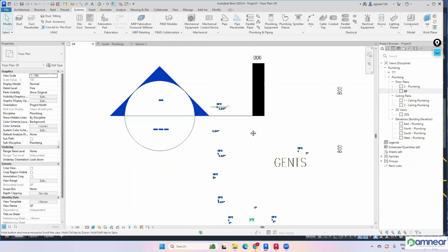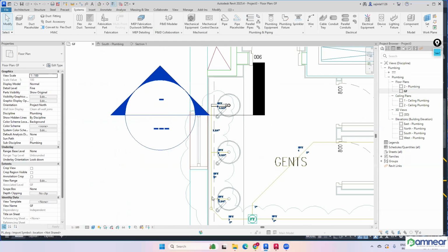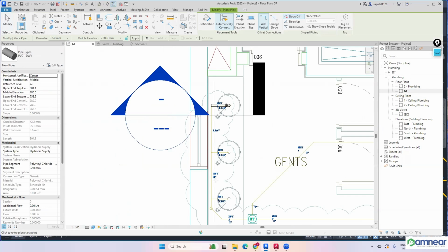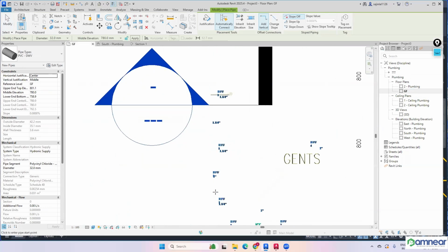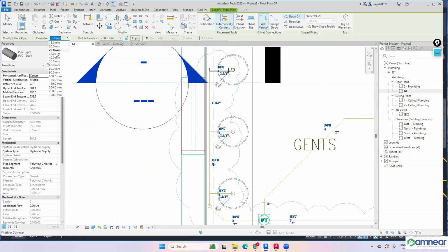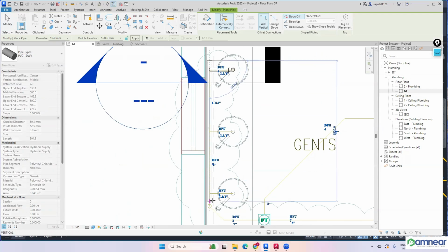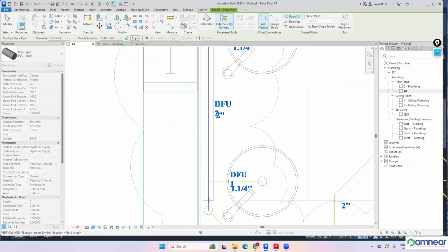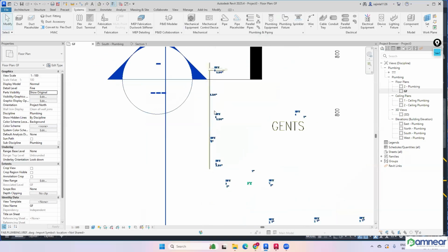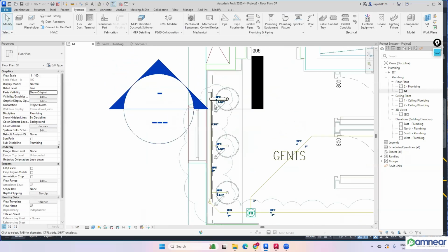I need to provide, because all these three wash basins are connected to a single common pipe only, I'm selecting a pipe. Let's say the pipe is 2 inch only. See, this pipe is 2 inches, it's 50 mm. This one I'll be placing nearly at 500 with respect to the ground floor within the wall. I'm explaining until there. Slope I am not introducing. As I told, in plan it is not mandatory, but wherever it is required, I will provide it.